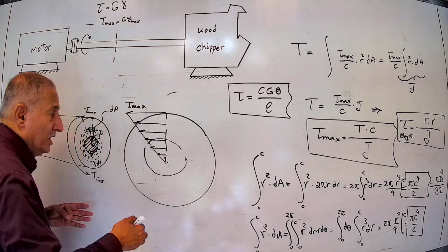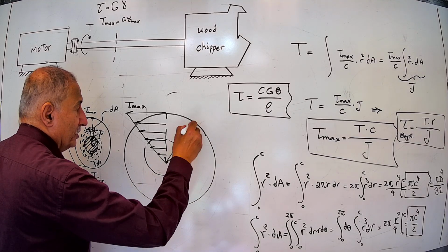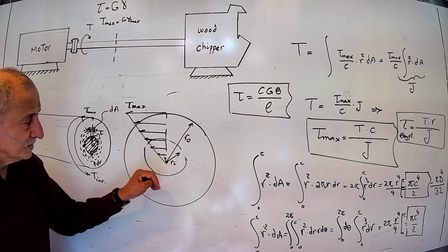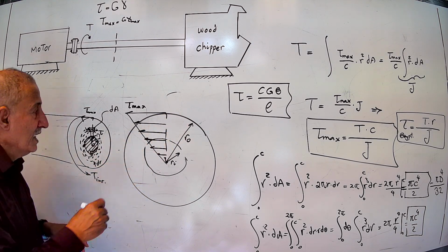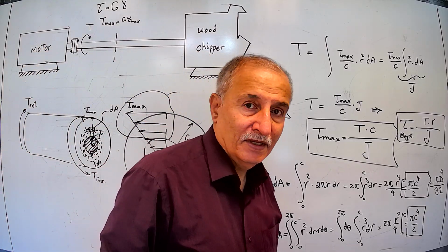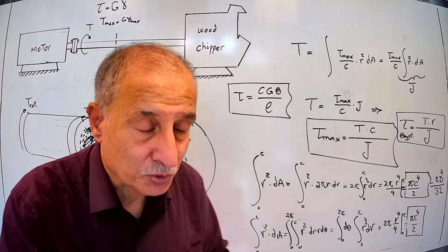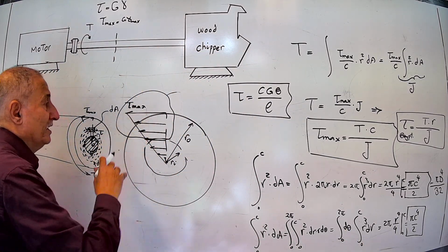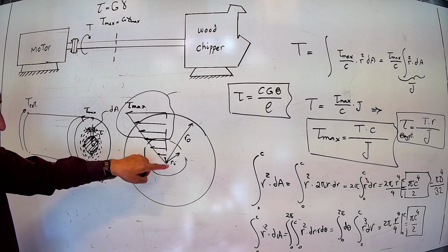It is better to make a hollow shaft from internal radius to outer radius, and send the material from the core to the outside, because the outside carries larger shear stress. I need the material, like soldiers, around the outer surface to carry the maximum shear, but not here. Here it is close to zero.